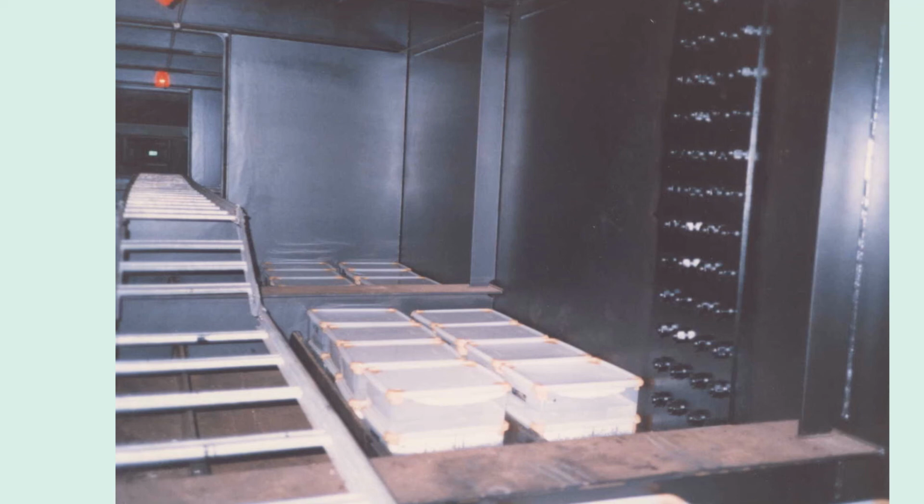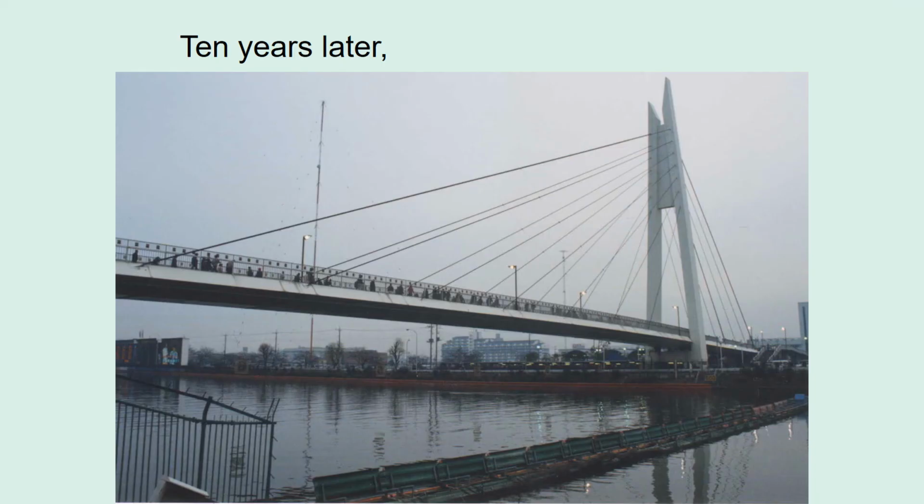However, I was worried about one thing. The inside of the box girder is very hot and humid, and would deteriorate the sealing of TLDs. It would have a durability problem. 10 years later, I anxiously checked the bridge. As I predicted, some water in TLDs evaporated and they are not working.